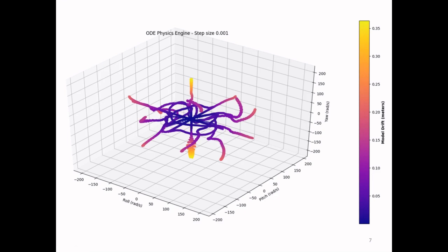So the goal here is to excite all the different combinations and all the different angular velocities that the aircraft can actually achieve by going through the permutations of the different control signals. For example, the first permutation would just be that we want 100% throttle on motor 1 while the other 3 motors are just at 0, and then that would be one of these trajectories for some specific angular velocity that it ends up achieving.